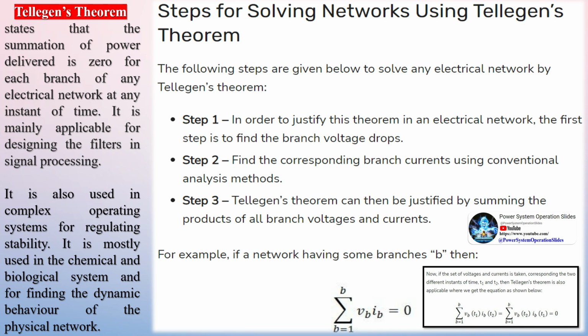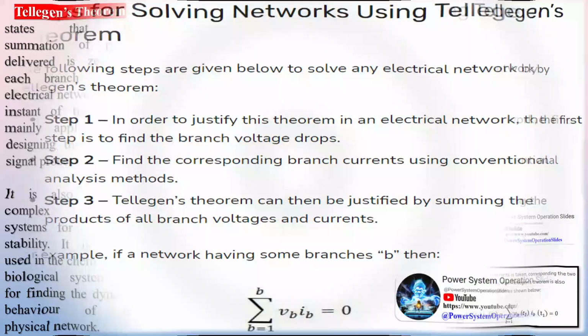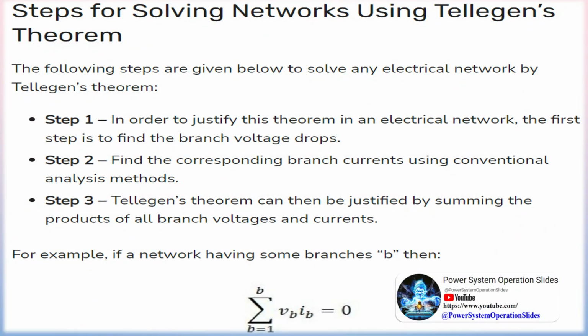Similar to the DC circuits, this theorem can be applied to the AC circuits which contain linear elements such as resistors, capacitors and inductors. Similar to equivalent Thevenin's resistance, equivalent impedance can be obtained by replacing all voltage sources with their inside impedances. Which theorem is applicable for linear and nonlinear circuits? Substitution theorem is applicable for linear and nonlinear circuits. How do you use Tellegen's theorem?